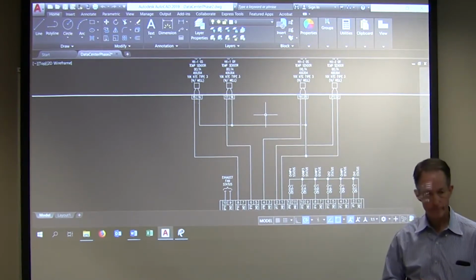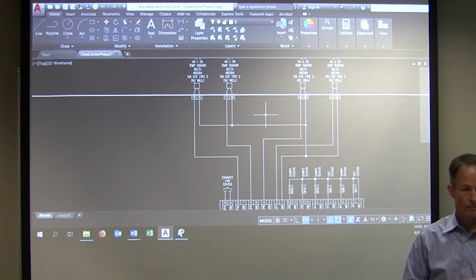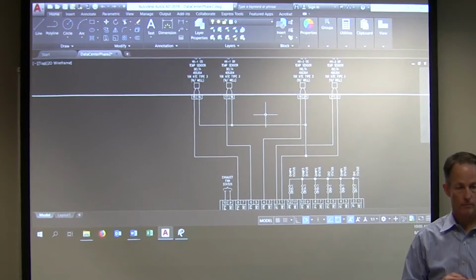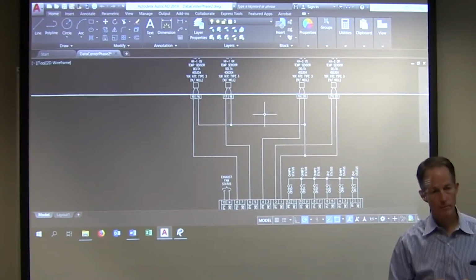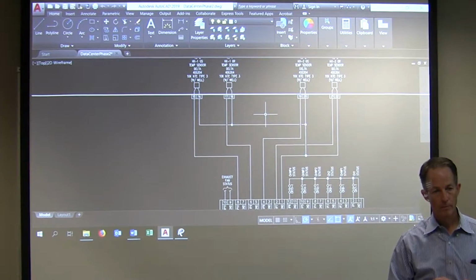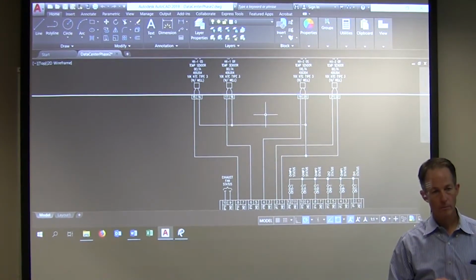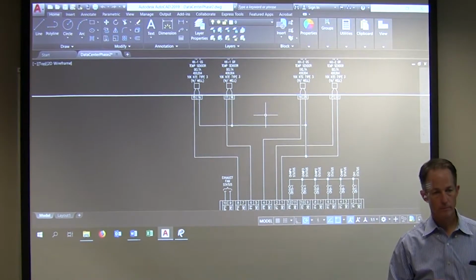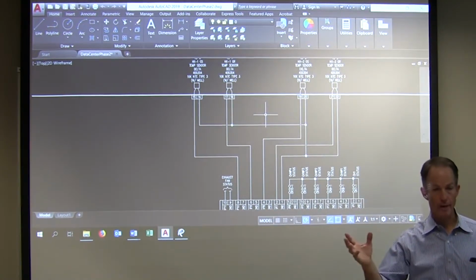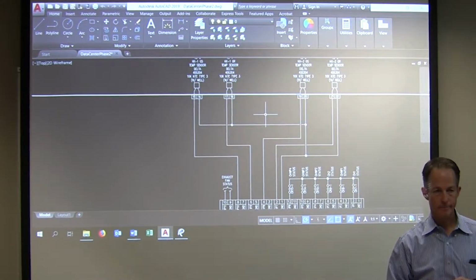So just today we have a unit in the Elford building. One of the four compressors was locked up and we tried to reset it. So we turned on the power. It was working before, I mean the old compressors, the old three. We turned them off and after that we put it back on and it didn't do anything. We spent like 3 hours there just trying to figure it out. And we checked everything, and they said air proving switch. It wasn't working. Compressor switch. You had a safety, but it wasn't that, because the outdoor machine was reading that, but the other one wasn't communicating with the indoor. So you had a problem from the outdoor to the indoor, even though things were right, that link wasn't made. Exactly. So when we turn on the power, we reproduce that problem.